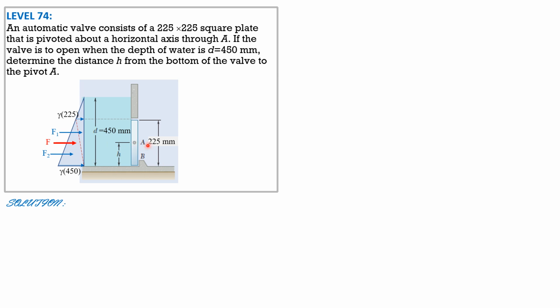So when we say just above, it means that F just passes through above A and its moment is 0. And the moment of the resultant F about A is 0, it is also the sum of the moments of its components. One is clockwise, the other is counterclockwise. So these moments of F1 and F2 have opposite senses. Then this is again 1/3 of 225, 75. F1 is also 75 from the top.